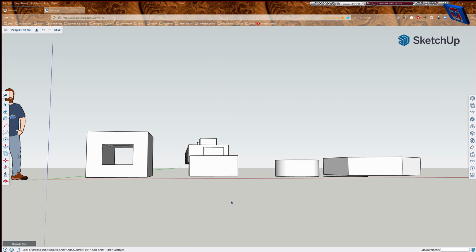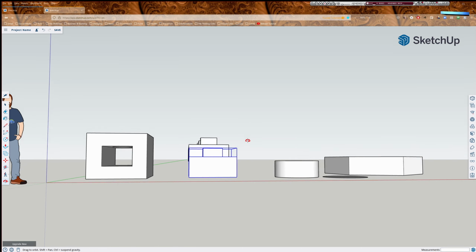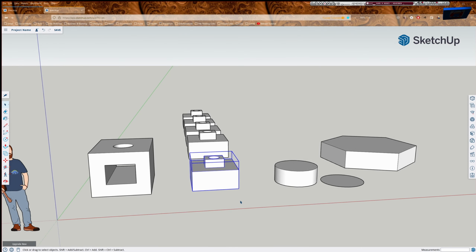Now you've also got a rotation tool, which gives you a little more flexibility. So if I wanted to rotate something, I can come down here. Oh, sorry, come down here to our rotate tool, or you can hit the letter Q. And you'll notice as you move it to the different faces, it's changing what axis it's grabbing.